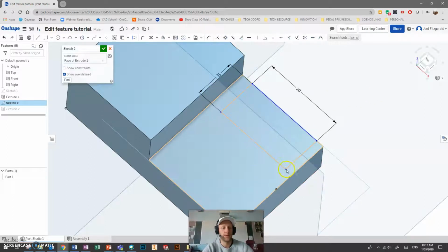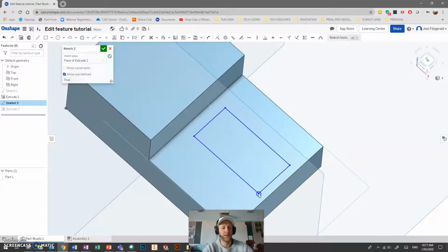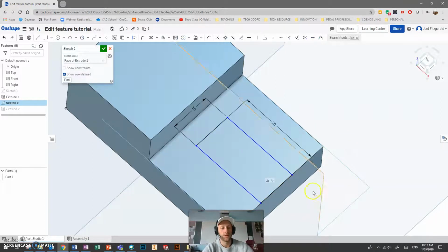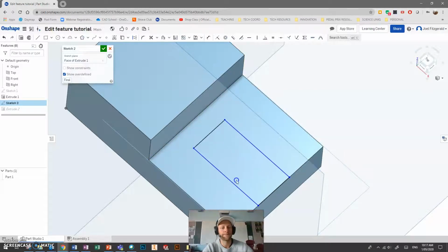That's useful. Now I'm going to move this over towards the center, which is where it's positioned. So I'm going to now pin this point back to this line. And you can see that this line and this line now become black, so it's constrained in that direction, but I can still shift this along the line.